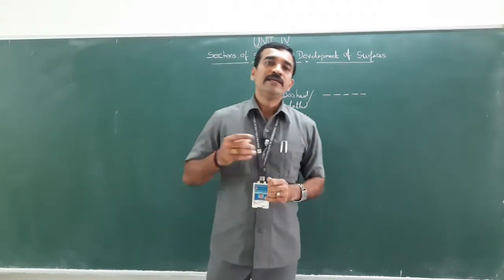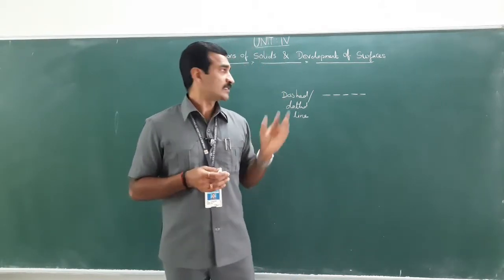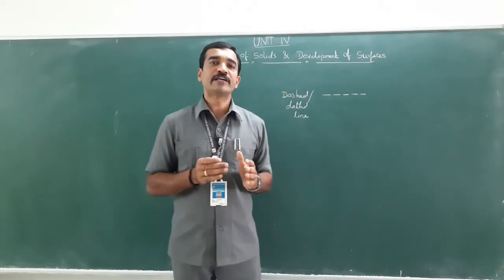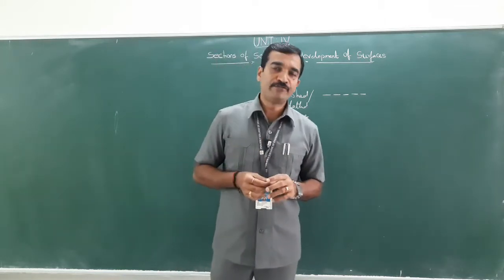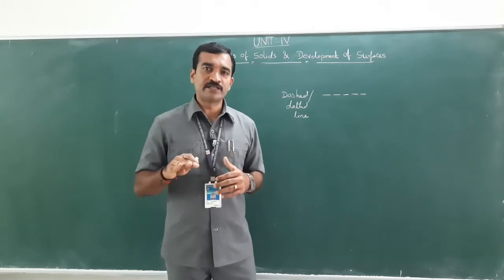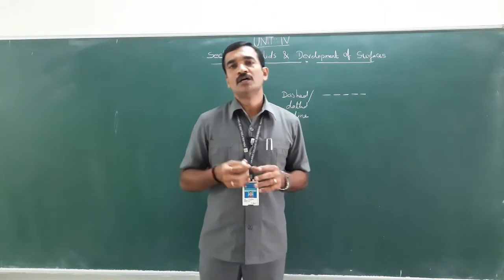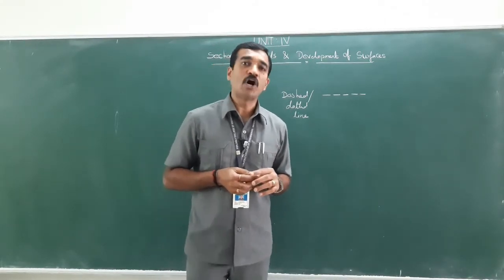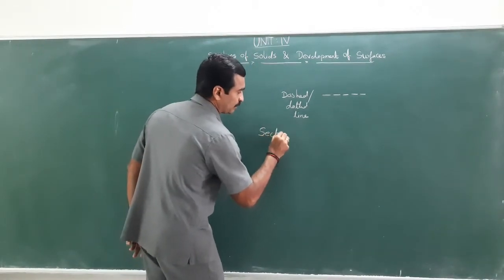When the interior of the object is complex, these dash lines or dotted lines are numerous. Therefore, the drawing is difficult to interpret. So, in order to overcome such difficulty, it is imagined that the object is being cut, completely or partially, by an imaginary plane called the cutting plane or section plane.